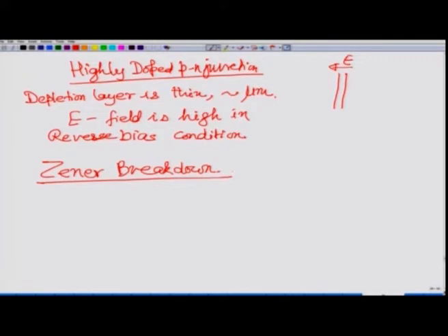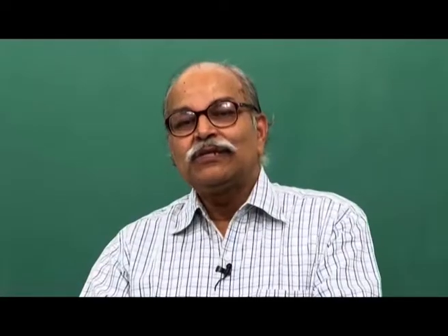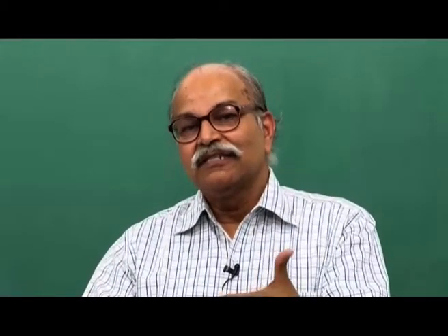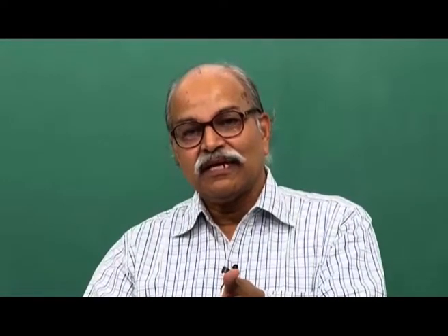Zener is the name of an American physicist, who studied these breakdown phenomena in insulators, and then those studies were extended to semiconductors, Pn junctions and so on. And now this Zener breakdown is used for certain kinds of applications, and the Pn junctions which use this Zener breakdown for the application are known as Zener diodes.